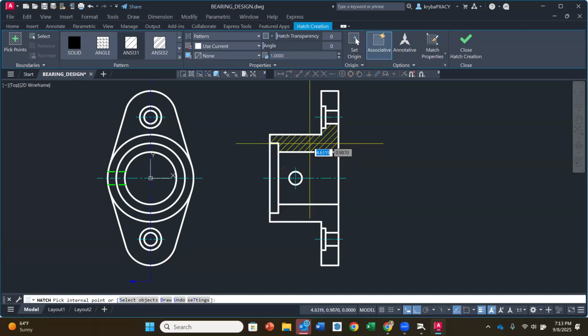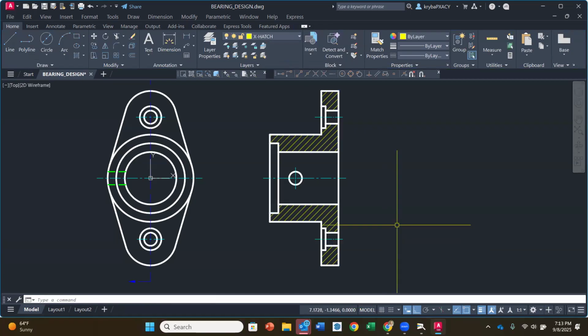All right. So now I am going to left click in all of the areas for which I have hatching, or where, when I slice this, it's going to cut material. Okay. So I'm going to hit escape there when I'm done. Now, if you don't have closed edges, if you have lines that are overlapping, it either might not hatch in those areas that you go into, or it's going to go beyond the borders. That's when you know you don't have good geometry. So that's a good test. Okay. All right. So that, I believe, do a save, and that is our final item.